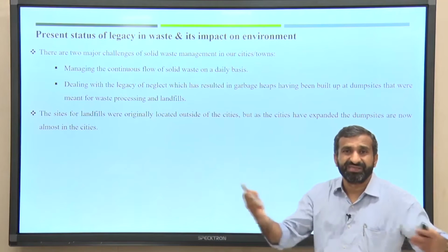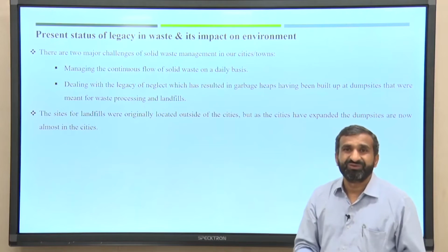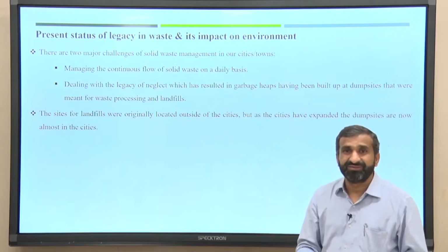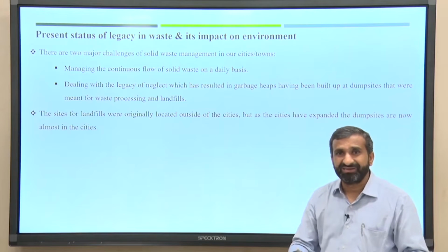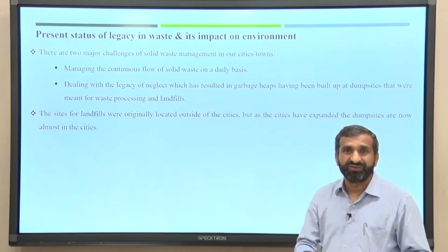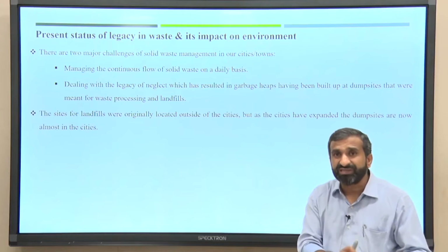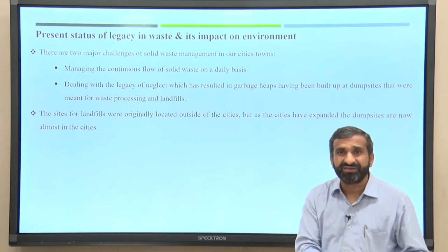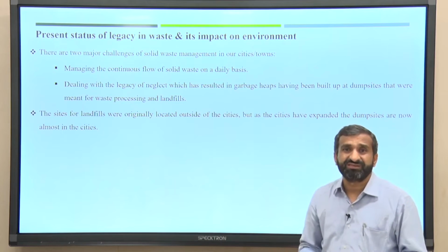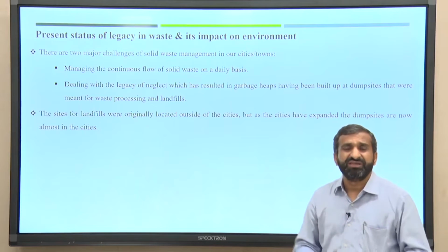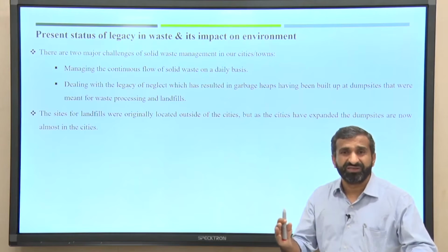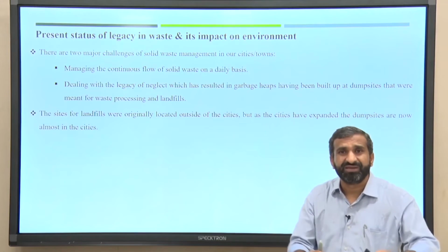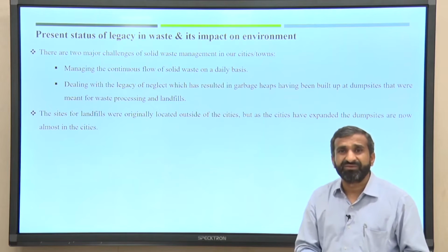Because the cities have extended so far, the problem is that the dump site is almost in the middle of the city. Now that waste becomes a huge issue, because, as I told you in the previous lectures, monitoring is required for 20 to 25 years after closing of the landfill, and again for 15 years, and no construction or habitation should be allowed in that area. From the start, almost 40 years you can't live nearby those areas; they are not habitable.